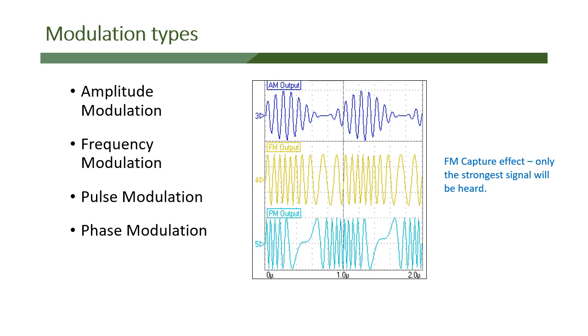There are, of course, other modulation types. We have amplitude modulation, what we just discussed. We're changing the amplitude of the carrier wave with respect to the lower frequency intelligence. Now, amplitude modulation is susceptible to man-made and natural RF noise, like thunderstorms or lightning. Whenever you have a lightning strike, you will see the amplitude of an amplitude modulated wave change as another waveform is superimposed onto it.